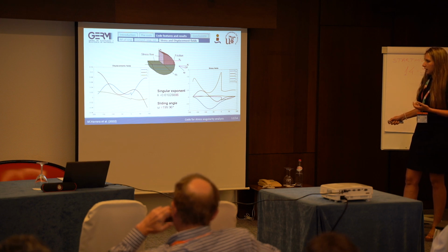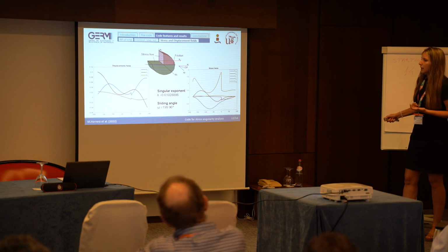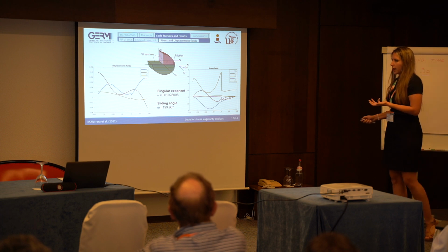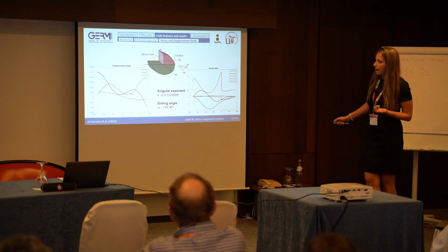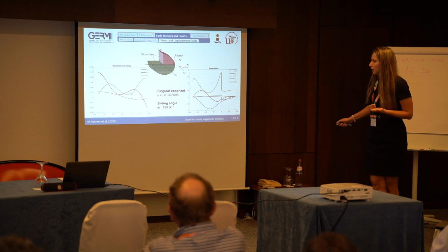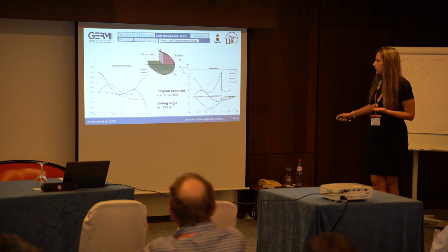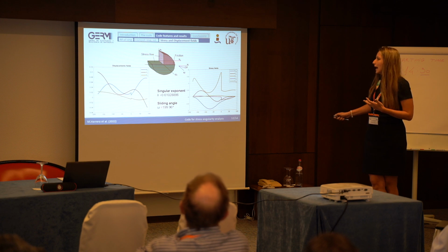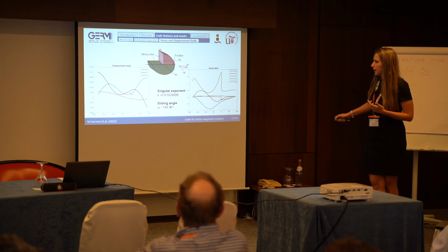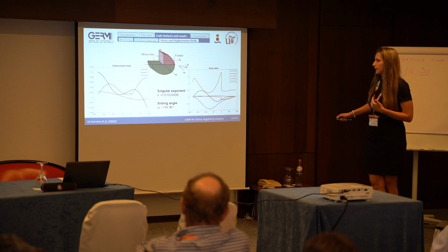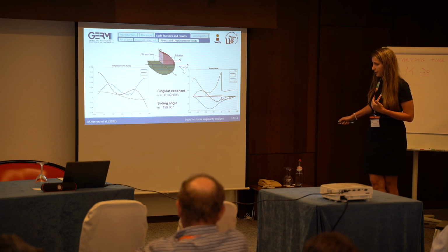We can see here in the displacement field, for example, that it matches the boundary conditions that we have imposed, because you have a displacement at minus 180 degrees and at 90 degrees, and in θ0 you have a contact because u theta, the normal displacement, is constant across the jump from one material to the other, that is zero.